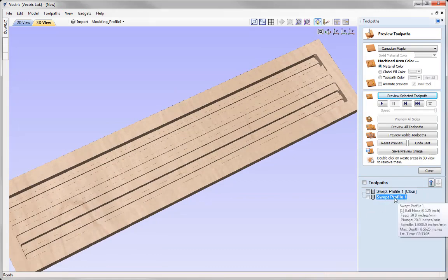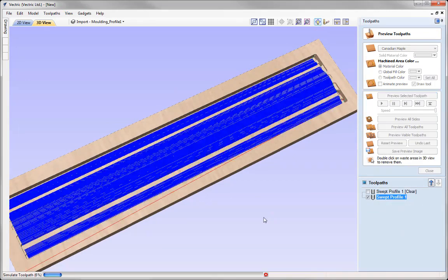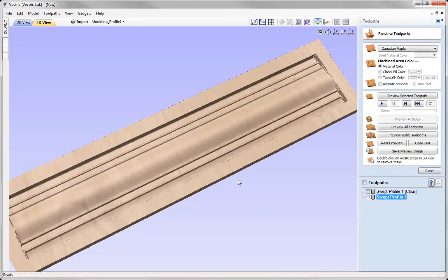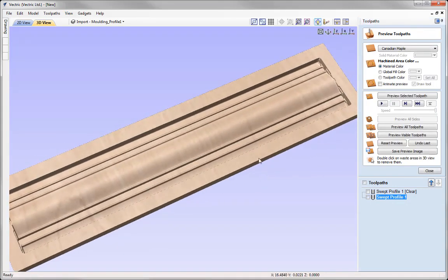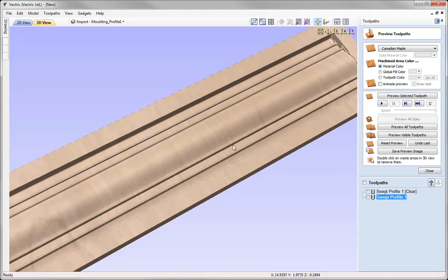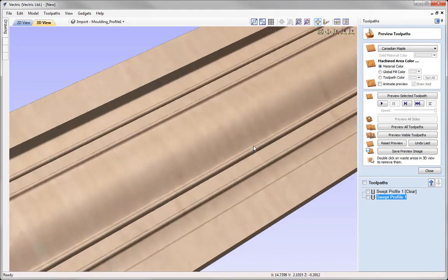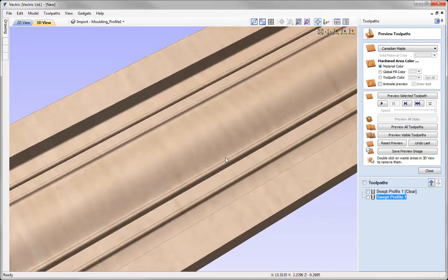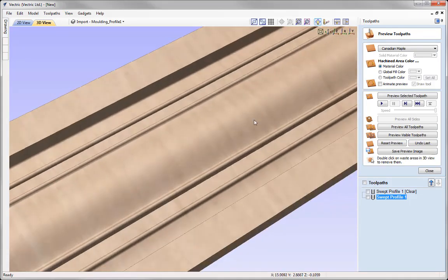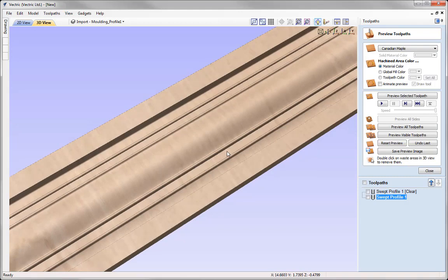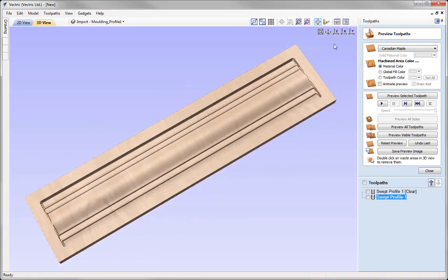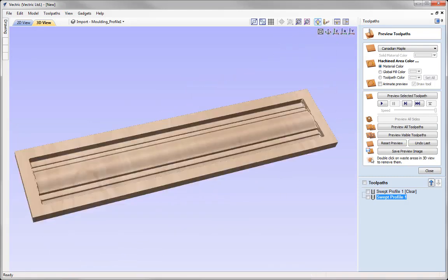And then we'll take the finish profile here, we'll preview that toolpath. So again, it's missing those flat areas, and so we can see that we have a much cleaner finish in these flat areas that we've got here. And so it's more efficient, and it provides us with a much cleaner result by using the machining flat regions section. So let's just put that in the ISO view.